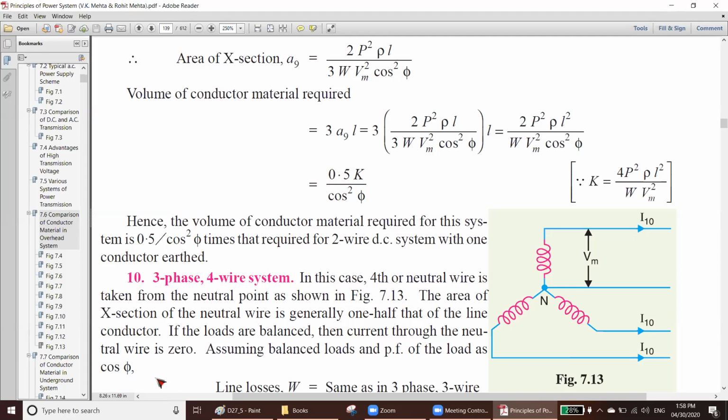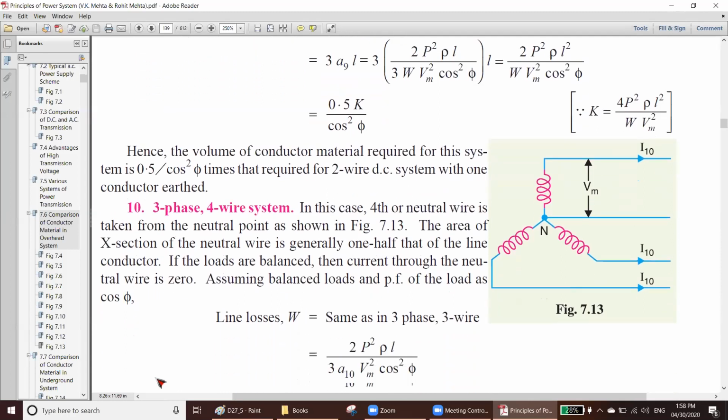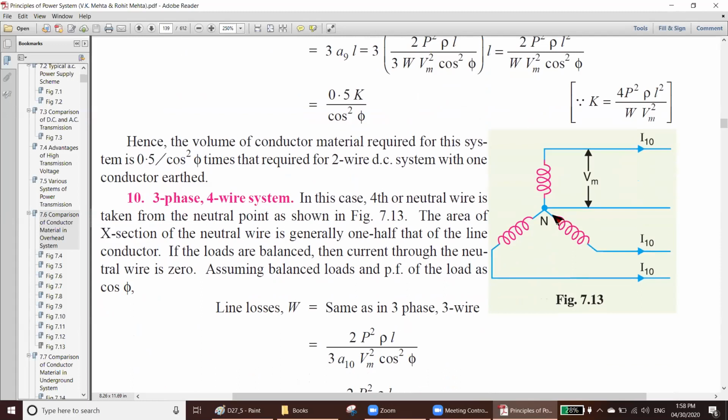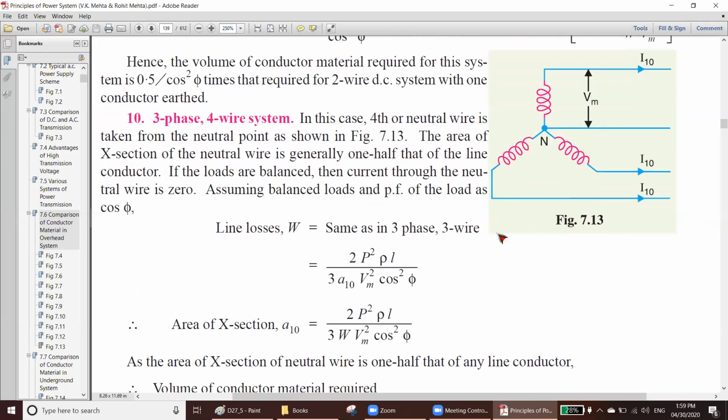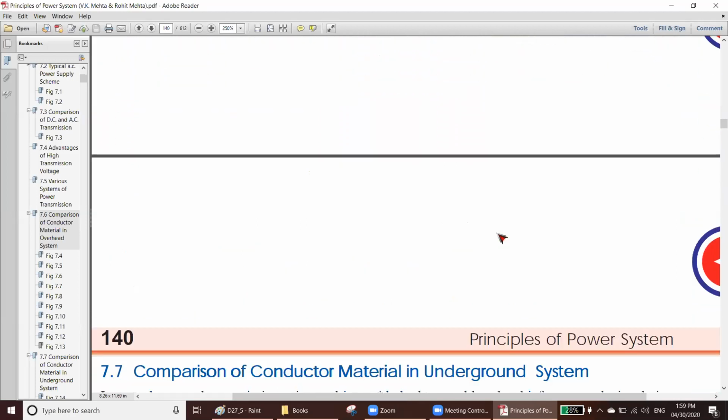That's why it is universally adopted everywhere. And you have another system that is called 3-phase 4-wire system. You can study by yourself. So what is the difference in 3-phase 4-wire? The middle earth position will have another line that will be called earth, or that will be called neutral. Now this system must be Y connected. You cannot make a delta connection here. Previously you could make either delta or Y, but here you cannot make a delta, because delta has only three connections, or 3 lines, 3 points. This one must be a Y connection. That is the only difference.